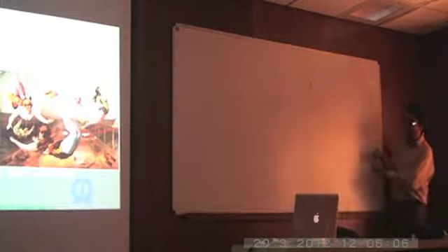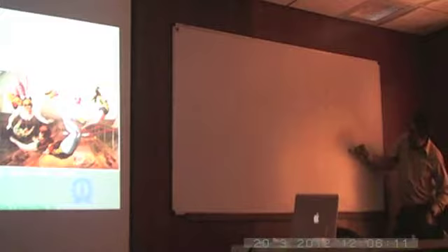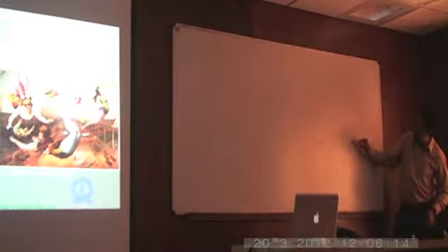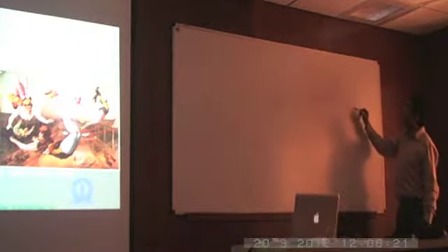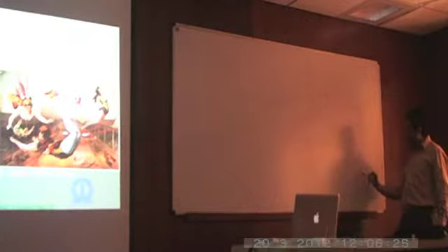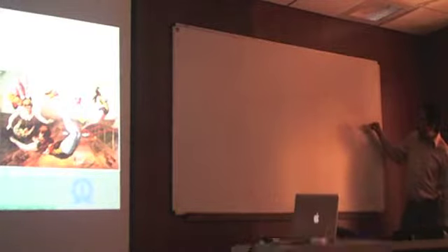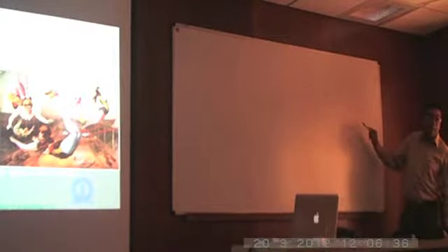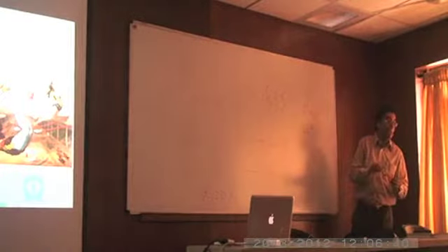So it means that this particular effect is going to be much larger compared to this. But you should also take into account the difference between these, okay? So you see, this is the stiffness that you're talking about. Here you're talking about an EI33 kind of an equivalent, whereas here you're talking about an EI22 equivalent. So in terms of the contribution to the energy, they will be of the same order. One of them is increasing in the product, the other is decreasing, so that you basically have the same order of contribution to the energy.